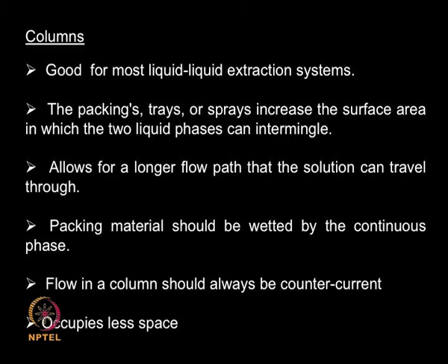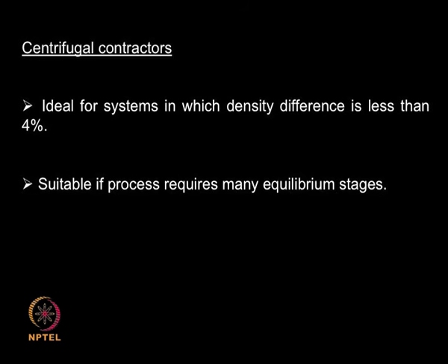But one important point is the packing material should be wetted by the continuous phase. So you cannot have a very low flow rate such that the packing is not wetted at all and there are some dry regions, then you are not efficiently making use of the packing. Generally counter current is preferred because you get better separations or better efficiencies, and of course as I said it occupies less space as well.